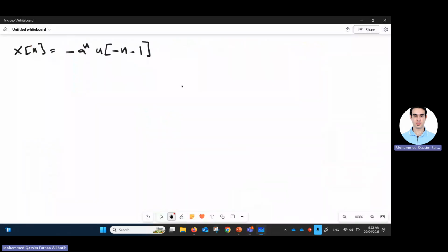Before applying this summation and everything, let's try to understand this unit step function. How to do it. First of all, we know that there is a time reversal because I have negative n. So my unit step function is going to be something like this. And we have zeros at these points, and the amplitude is 1 for all. Now, what will be this point?